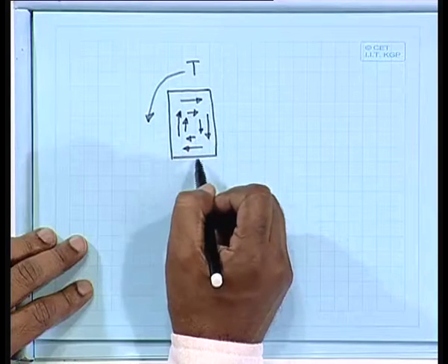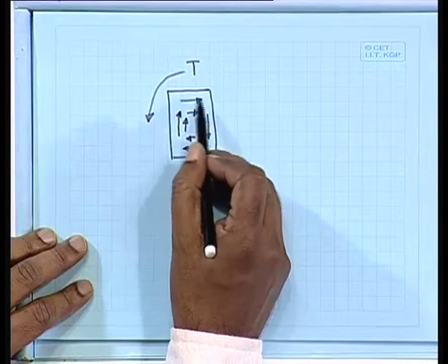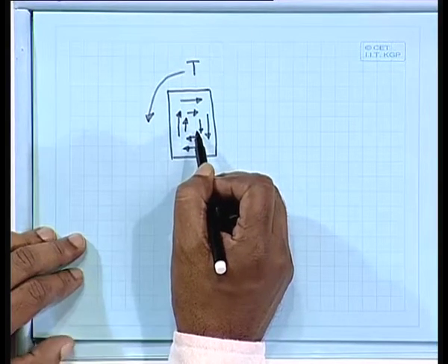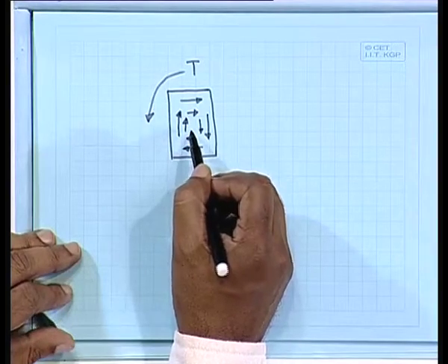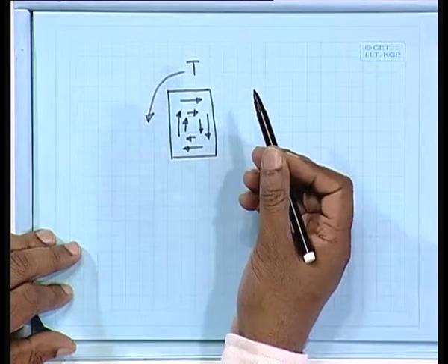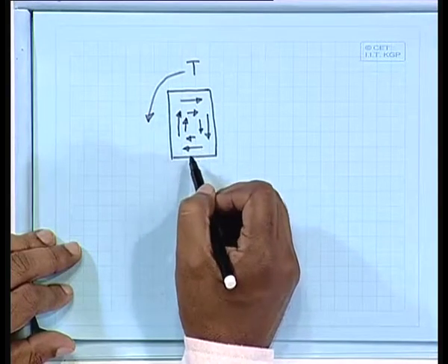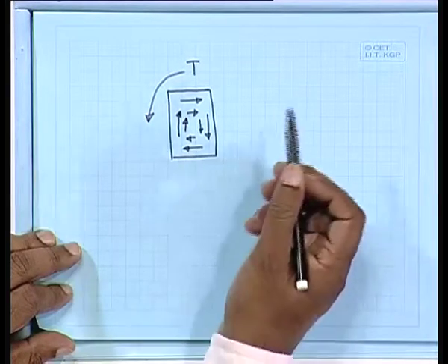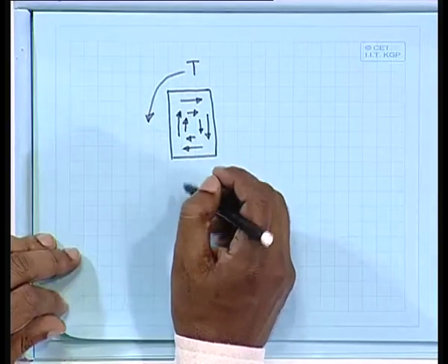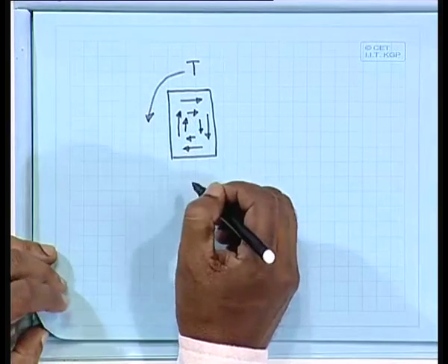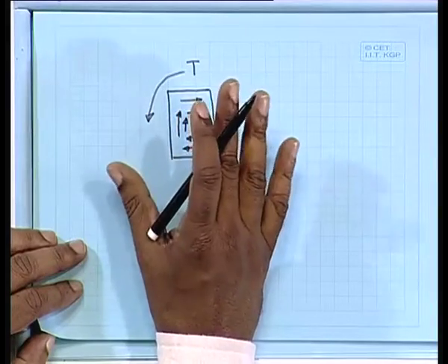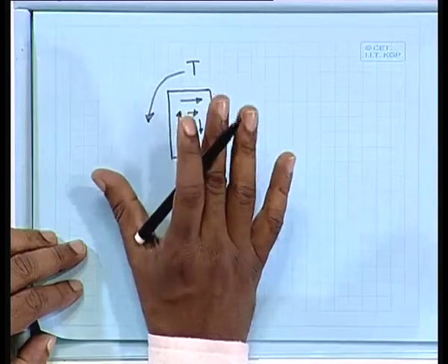If the shear stress is developed here, we can resist it by providing longitudinal reinforcement, which is equivalent to your bending moment, and the stirrups, which is your shear reinforcement, and that we shall do here.